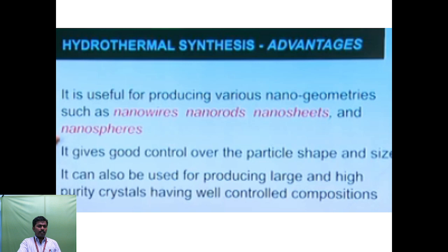So advantages of hydrothermal synthesis are it is useful for producing various nano geometries such as nanowires, nanorods, nanoseeds, nanospheres. It gives you good control over nanoparticle shape and size. It can also be used for producing large and high quality crystals having a well controlled composition.